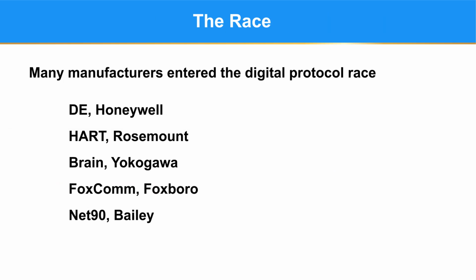Now for just a little background on HART. Manufacturers were putting computing power in the instrumentation, but couldn't come to an agreement on how to get the information out. The technical term used at that time was stranded data. There was a race between many manufacturers to come up with a protocol for the microprocessor-based instrumentation. Rosemount's entry into the race ended up to be the protocol of choice, as it was simple and did not interfere with the 4 to 20 milliamp signal.